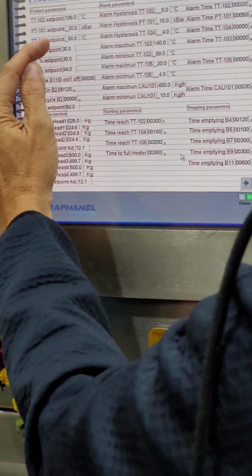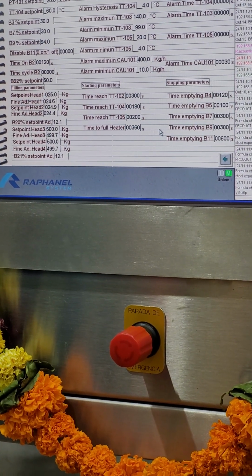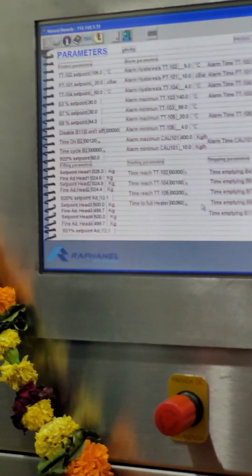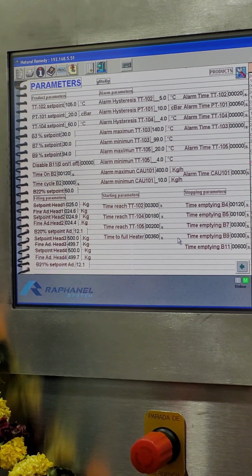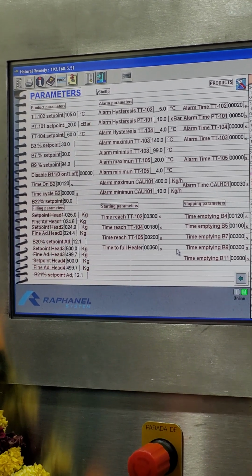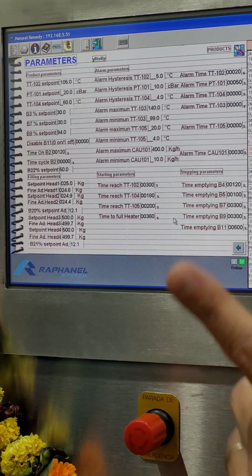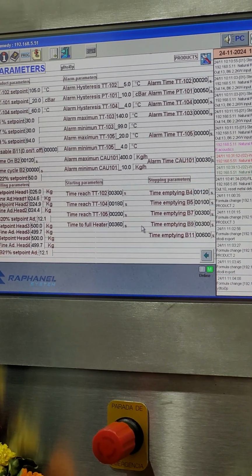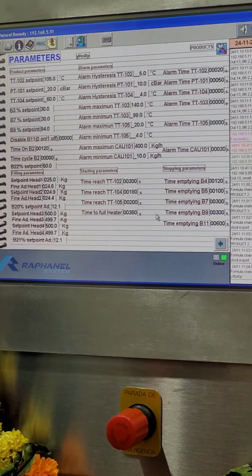This temperature, TT134, is the dryer. For the dryer, you have to check the moisture and decide whether to increase or decrease, depending on the result that you want. People intentionally increase the moisture, because if your customer needs 10% moisture and you have 6% moisture here, if you increase it to near 10, you are obtaining 4% free material outside.